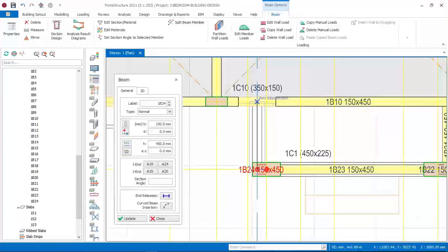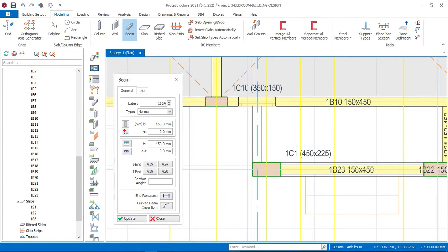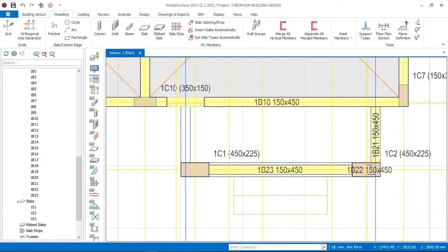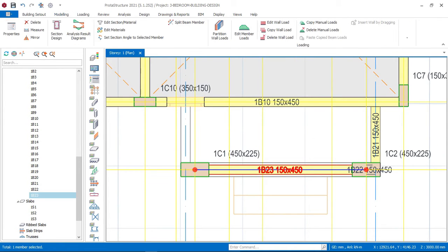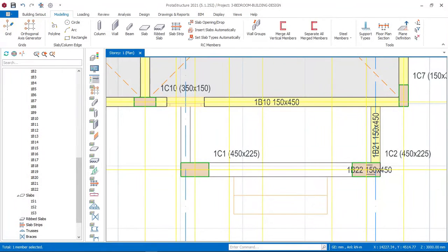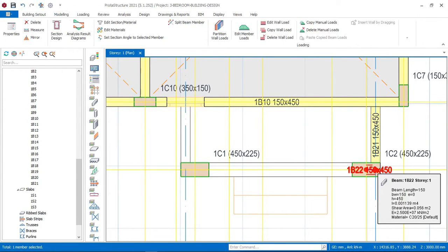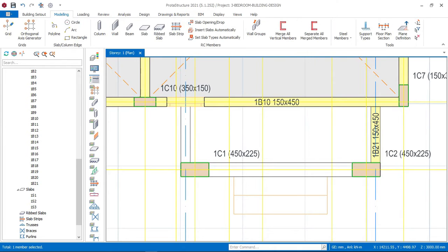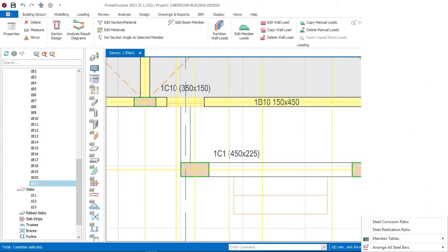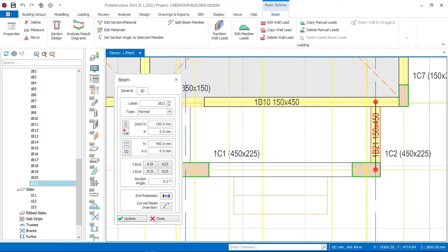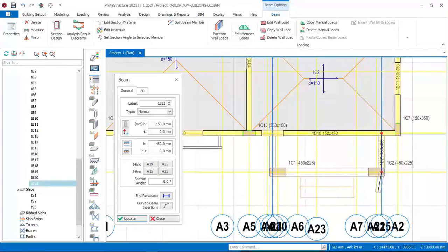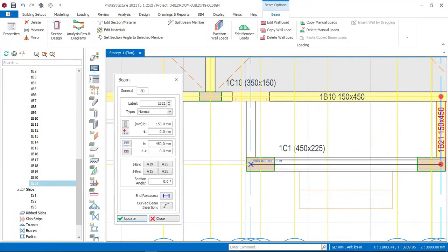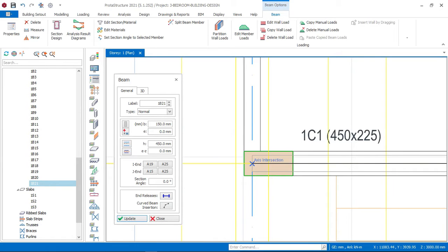Okay, so there's a mistake here, so just delete that right now and then check back this. Okay, there's a mistake here, so delete that and then take back this beam property. Remove this also and take back this beam property just now. Take this beam property and click at this point and then go all the way down here and click at this very point here.